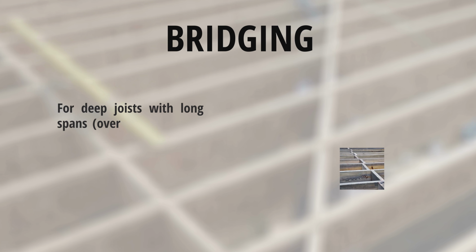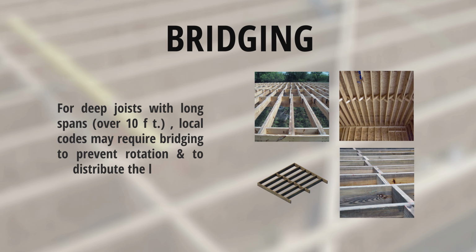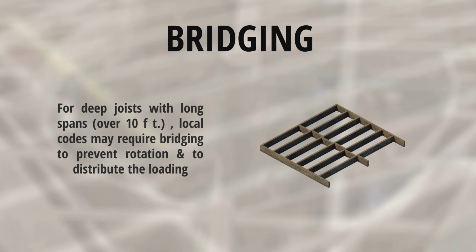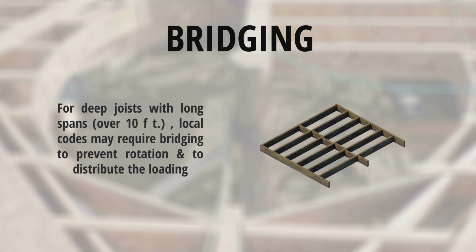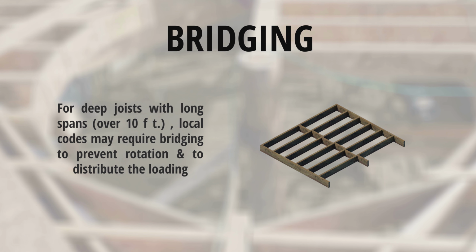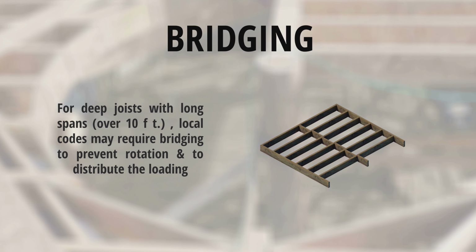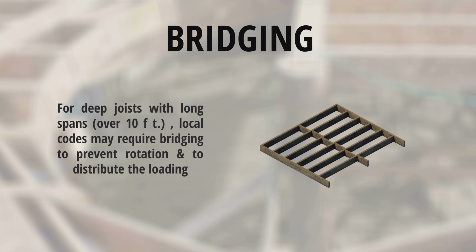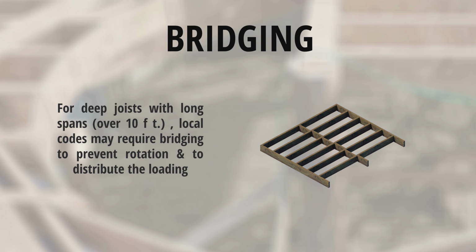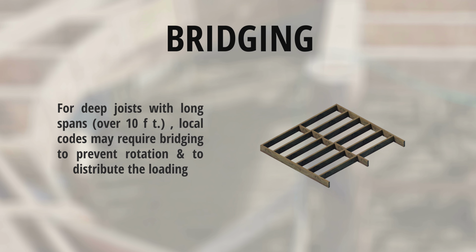Bridging. For deep joists with long spans over 10 feet, local codes may require bridging to prevent rotation and to distribute the loading. Let's reference this detailed illustration. Block bridging. Solid blocking from same material as joist is staggered for ease of nailing. Metal bridging. Metal pieces should not touch each other. Cross bridging. 5/4 inch by 3 inch or 5/4 inch by 4 inch or 2 inch by 2 inch or 1 inch by 4 inch boards are nailed in a cross pattern between joists. Pieces should not touch each other.